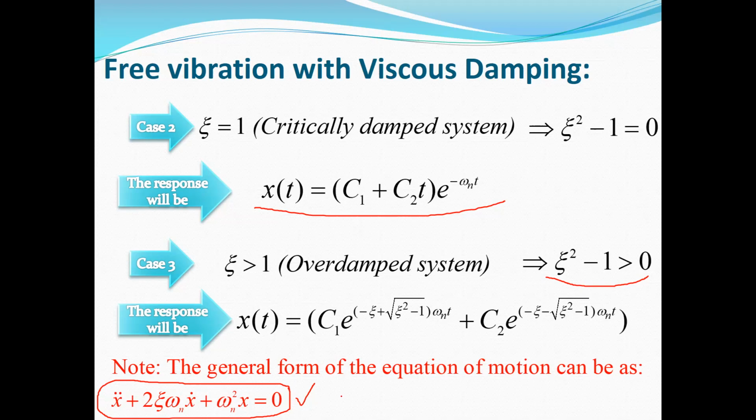So anytime you have the equation of motion in the exam, especially when you are short of time, you can use this point easily. You can divide the equation by the coefficient of the acceleration, or x double dot, and convert the equation into the new form. In the new form, when the coefficient of x double dot is 1, the coefficient of x can help you to achieve the natural frequency, and the coefficient of x dot can give you the damping ratio.